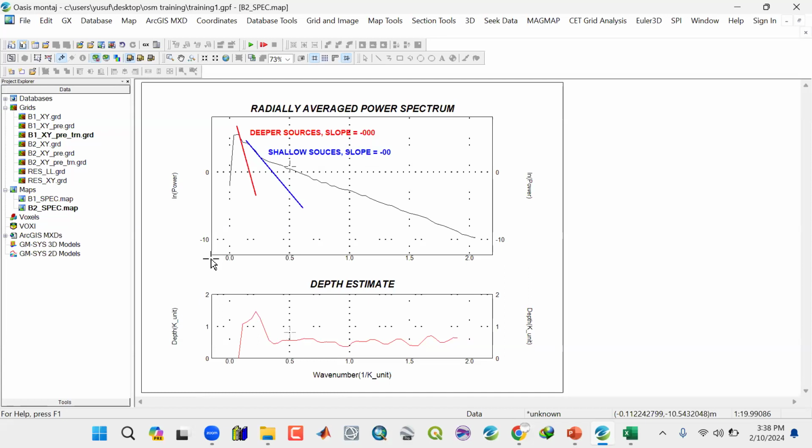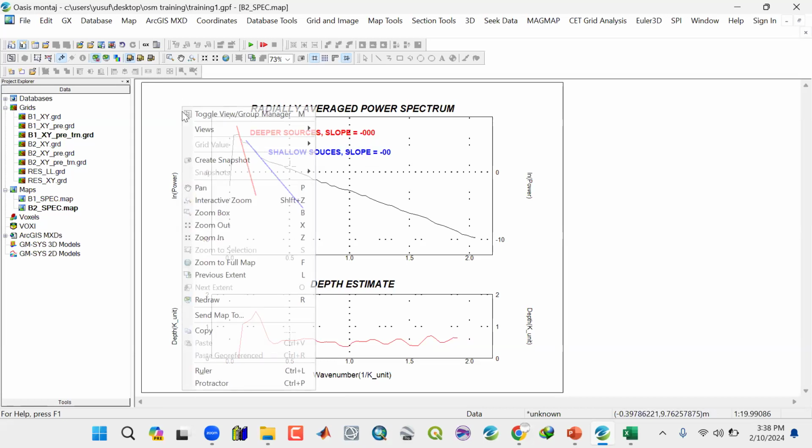Then I can also measure the length from here to here to confirm. How do you do it? You still right click. You see there's a ruler. Remember, I want to find the slope. What is the slope? Change in vertical over this. Let's go to the ruler first. If I click the ruler, I want you to look down here on my display. Can you see it? Start the protractor. Do you see it? So this part is what you're going to put at. Make sure you select this one first. Right click, then you go to ruler.